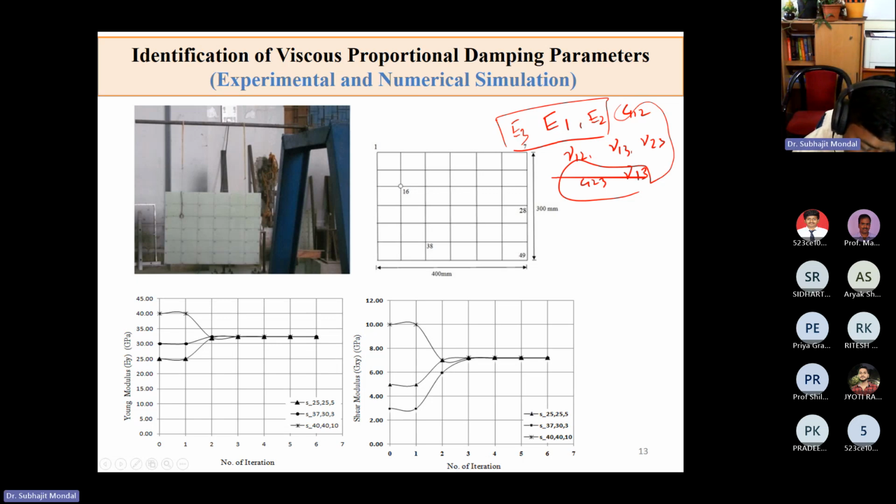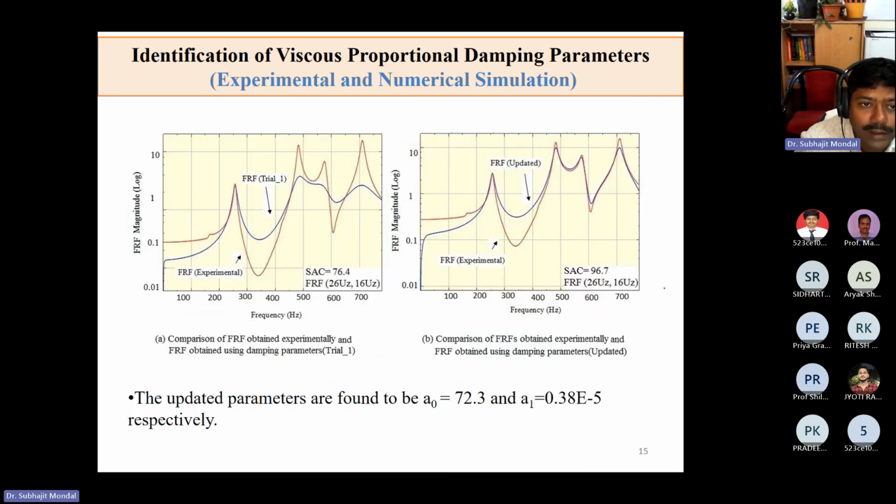Now the problem I'm going to discuss. If you have a plate like this, and you have a different pattern in that FRF, what can you do? Basically, you can update the mass or stiffness so that you can try to get the frequencies one by one. So here we have to go for updating using some model updating technique.